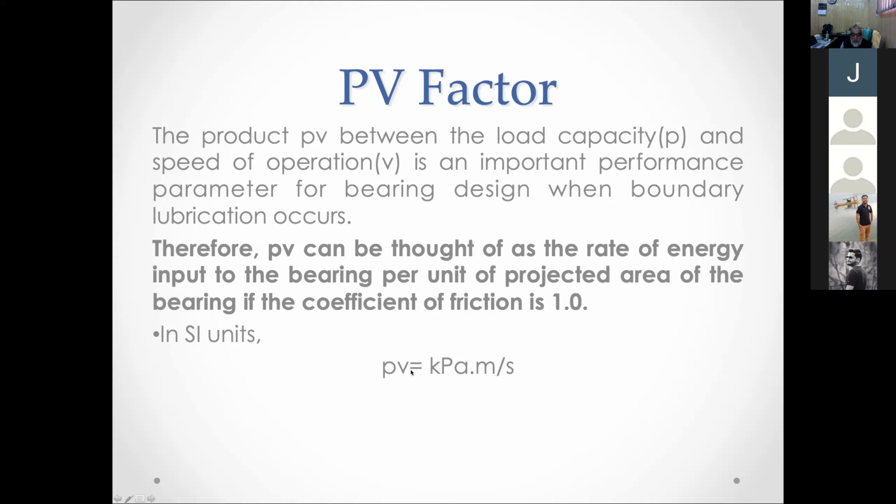In SI units, PV is equal to kilopascals meter per second. So units of this are pascals meter per second. So we represent PV factor by kilopascals meter per second. It is actually the energy unit, because if you divide force by projected area multiplied by velocity, it should come equal to this.